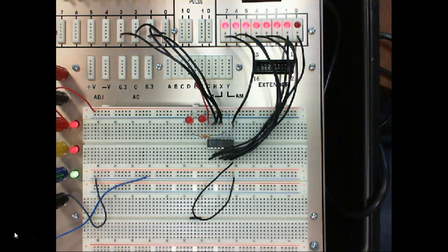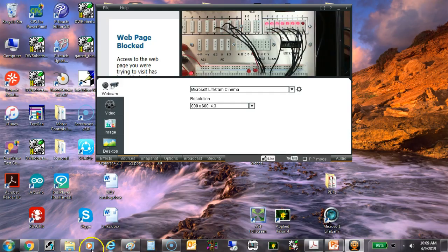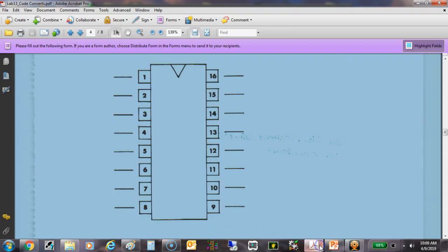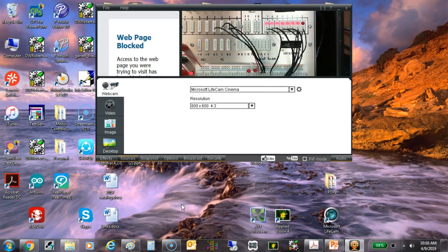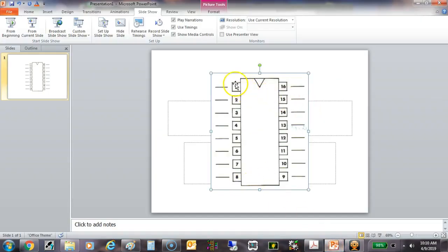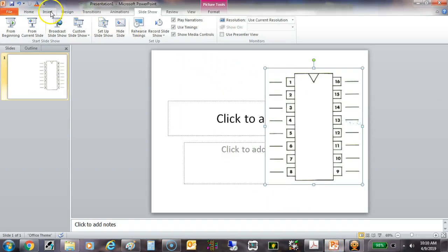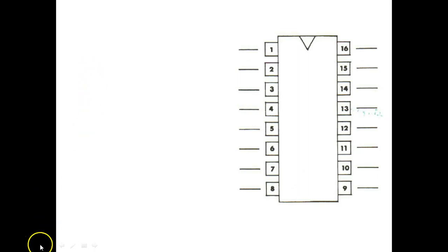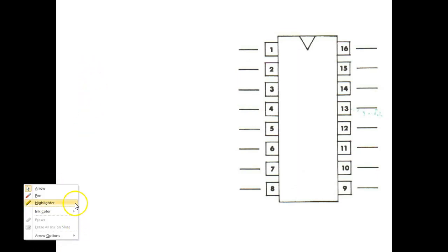So what we need to do is set up a truth table, and it should look similar to the truth table on the data sheet. The data sheet we've already looked at has inputs that go from 0 to 15, right? You need to leave yourself a pretty good deal of room, guys. That truth table is going to be pretty large.